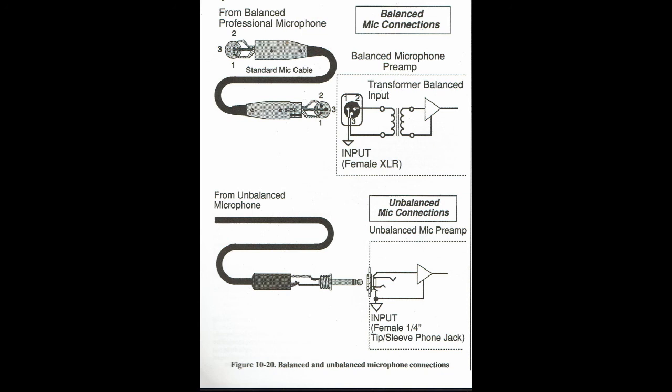To avoid this, there are a few rules of thumb that we can follow. If the cable run between the power amp or wall-mounted speaker outlet and the speaker is less than 50 feet, make the connection with 14 gauge audio hookup cables. Runs between 50 and 150 feet require 12 gauge cable. And then all speaker or power amp cable connections should be made with a specific type of connector.